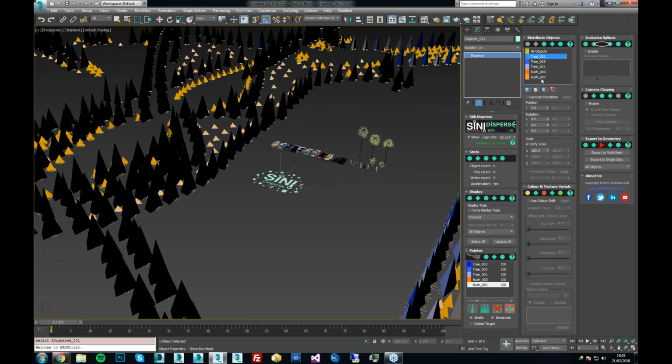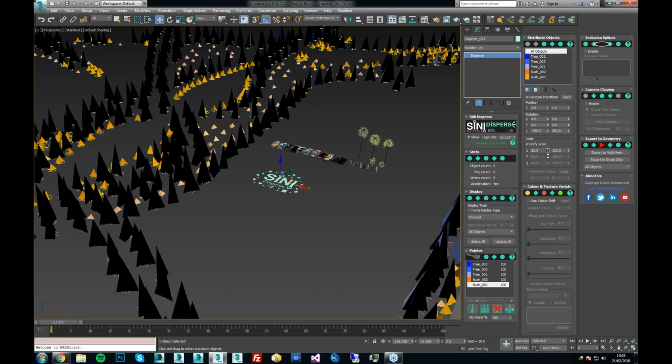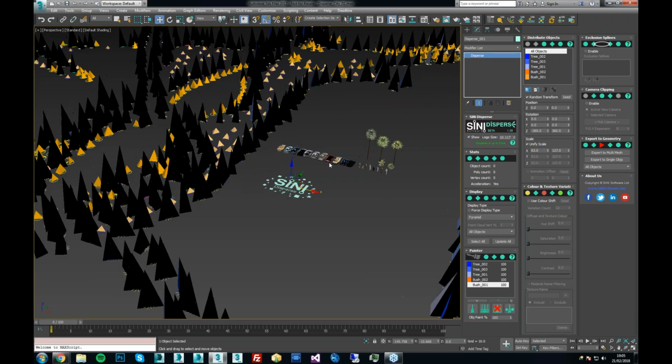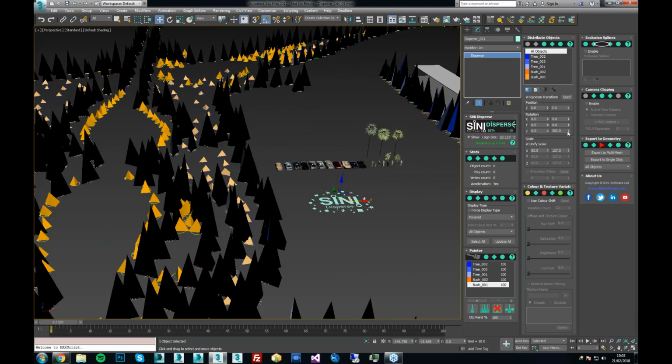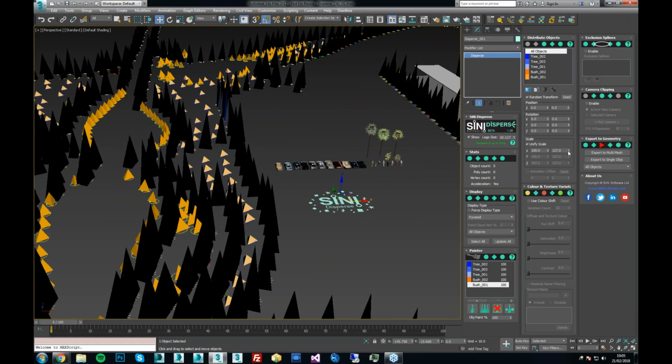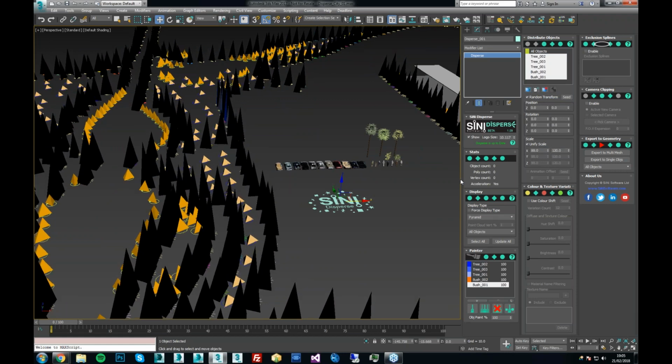With that done, you can now go in and set up transformations. I can turn on random transformations. I can give them rotations. I can scale them down and give that randomness you'd get with trees themselves. I'm going to turn that back off though, because I'm going to paint cars and people and different stuff. You can do these as individual transformations as well. So if I just wanted to have the trees scaled and I'm going to paint some people afterwards, it's not going to affect those.